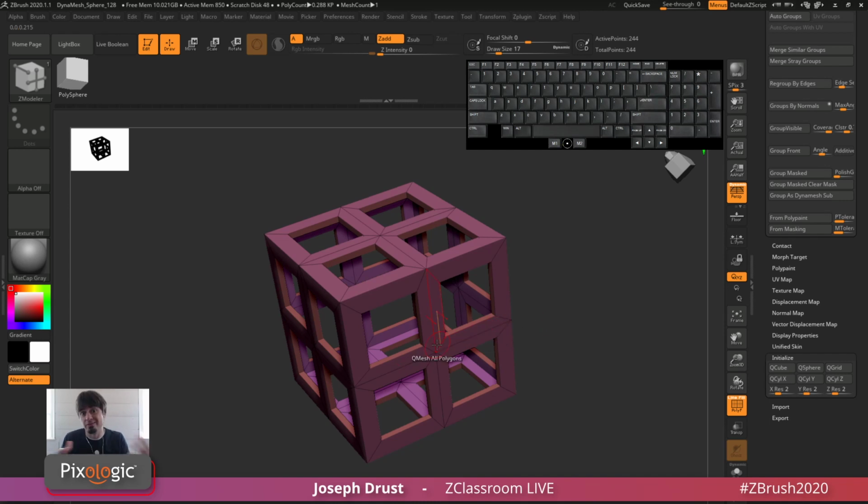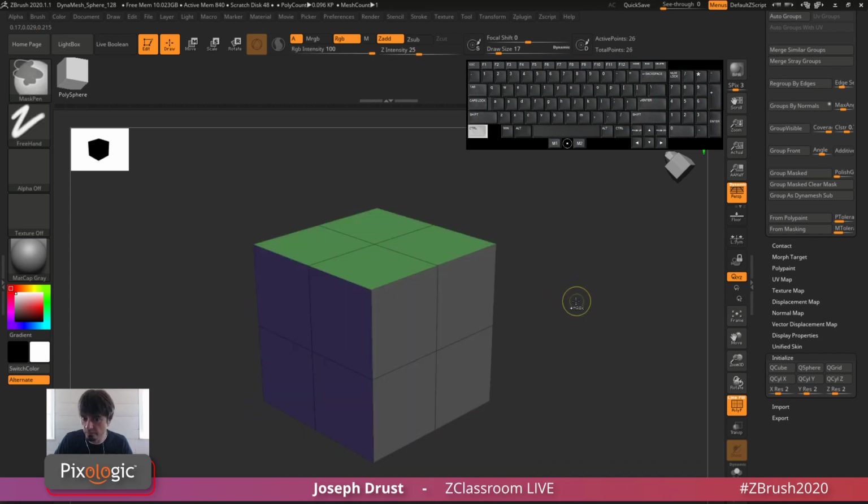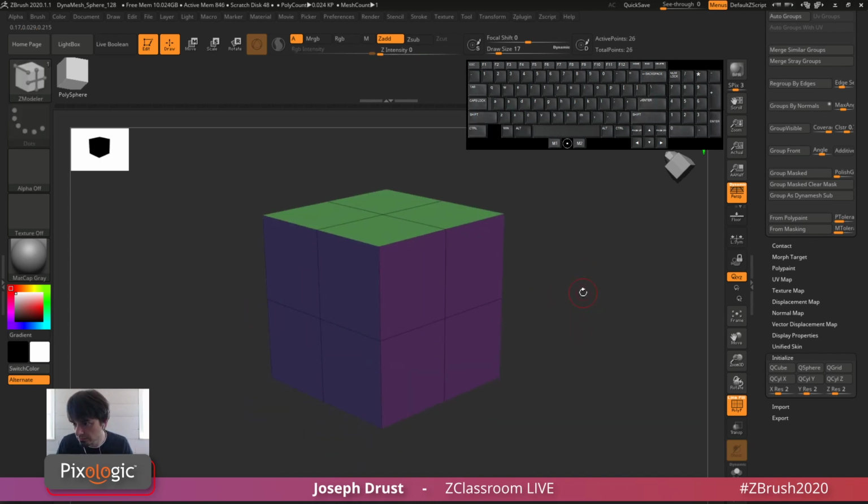However, you won't be able to get a flooded lattice out of this process, so you're not going to get any internal geometry. It's just looking at the shell of the object and then performing the inset and then the extrude. So, a little thing there. Dafu, yes, the Q mesh will fuse the verts if you're using that one, and extrude will not. So those are your two options there.